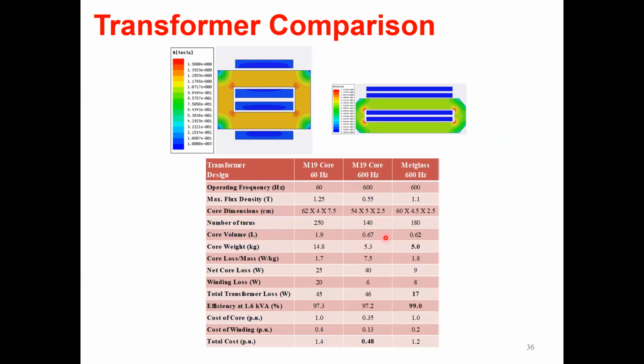But then there is one aspect which you will be thinking: what about the power electronics? Once we add the power electronics, this efficiency will come down to about 96.5 or something like that. But if you want a higher overall efficiency, we can go to this amorphous silicon core transformer, which is still not very expensive, but still much more efficient than silicon steel.